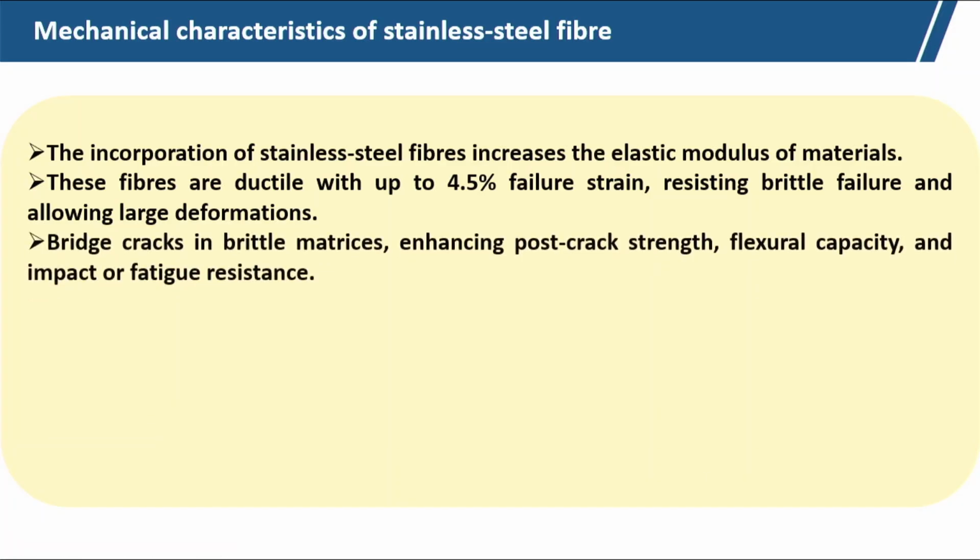So, it bridges cracks in brittle material. We can blend it with a brittle matrix, and in those cases it can bridge the crack, enhancing the post-crack strength, flexural capacity and the impact or fatigue resistance.